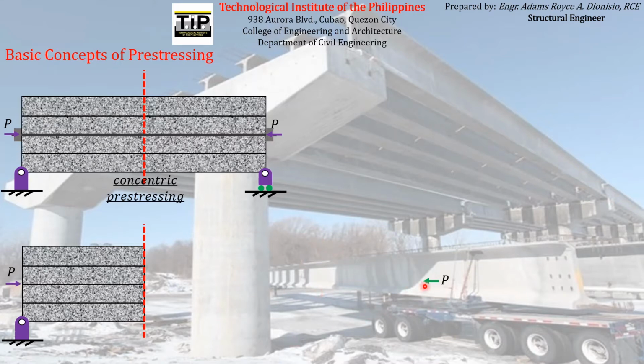So the internal force that will come out, that is acting on this cross-sectional area that balances this compressive force from the pre-stressing reinforcement, is this force P. Same magnitude but opposite in direction, and the line of action of this internal force coincides with the line of action of this external compressive force. Obviously this is a compressive force because it points towards the concrete member, so it compresses the member.